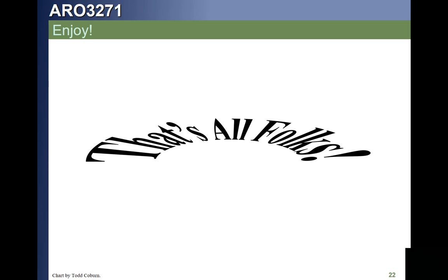That's how you analyze welds using the simplified procedure. Once again, we covered the simplified procedure for analyzing welds, and we covered how to evaluate the strength of the welds. That one slide is the key, where we're going to basically get the tensile strength, the yield strength, and multiply by the appropriate factors, take the minimum of those to evaluate our welds.